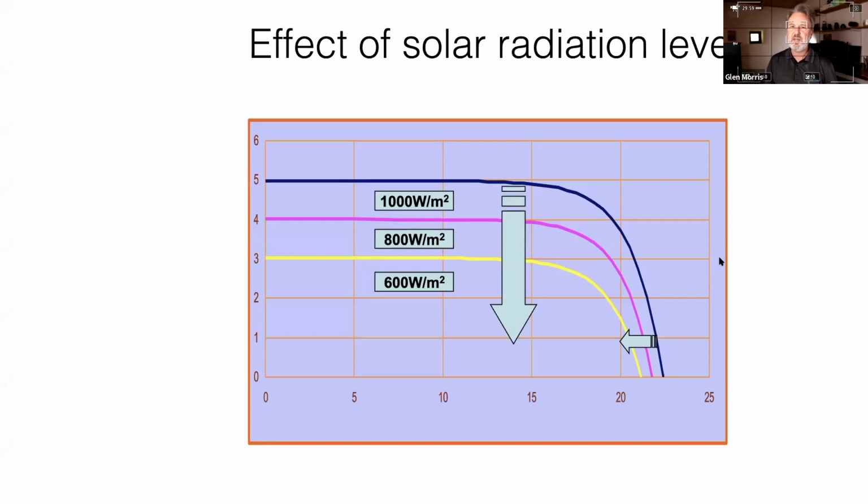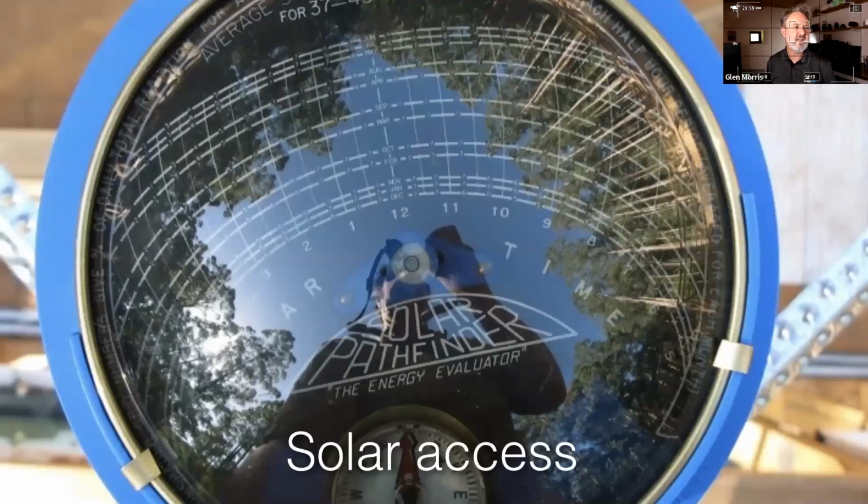the Solar Pathfinder gives you, maybe I'll just jump back so you can see it, in each tiny segment, each half hour of the day, the percentage of the sun's energy. It's probably pretty hard to read this unless you've got a big screen or good eyes, but around the bottom curve, which is December, you'll see either side of the words December, 7. And that means 7% in the period between 11:30 and 12, and 7% in the period from 12 to 12:30 of the day's energy is falling. And as it moves across to the afternoon, it's dropping 6%, 5%, 4%, etc.